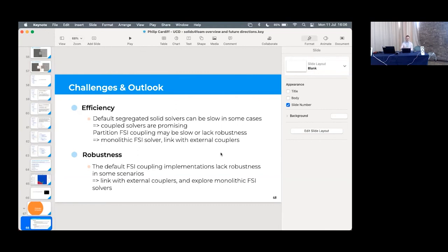But there are solids that solve for temperature, as long as you have a coupler that allows for that. For FSI cases, for incompressible cases, sometimes it's nice to have a little bit of compressibility because it helps convergence, like in arteries or something. So there are these weakly compressible solvers, like, I guess, sonicFoam is kind of weakly compressible. So there are weakly compressible ones, but they're basically incompressible. It just improves convergence for FSI cases with a bit of compressibility.